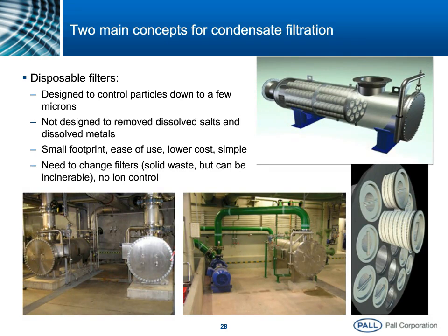The filter material is usually plastic, polypropylene being very standard, plus whatever contamination is captured in it. Of course, this contamination is very rarely nasty, hazardous, or dangerous. It's usually made of rust particles. You can see here a few pictures of actual power plant installations. These are full flow condensate systems on plants running anywhere between 300 to 550 megawatts, so you realize how nimble and small such a system can be.